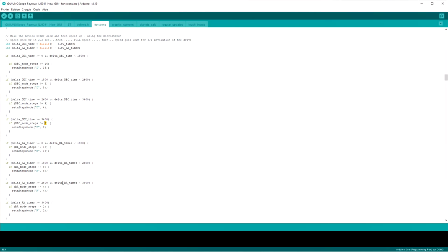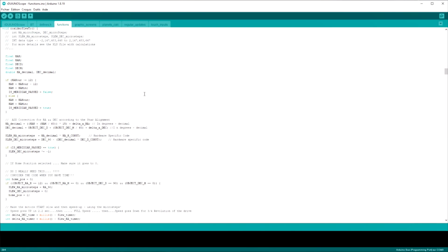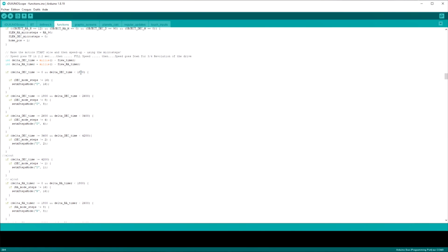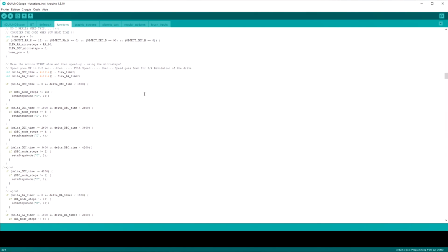The motors had a certain difficulty when entering mode 1 with the joystick function, but I tried anyway to use mode 1 with the GOTO function, and then running the motors at the maximum speed. Then I modified the code to add a new condition. Between 3400 and 4200 the motor is entering in mode 2, and when the time is greater than 4200 the motor is entering at full speed in mode 1. I prefer to add a new condition instead of replacing the 2 by a 1 to have a smooth acceleration instead of a big jump.